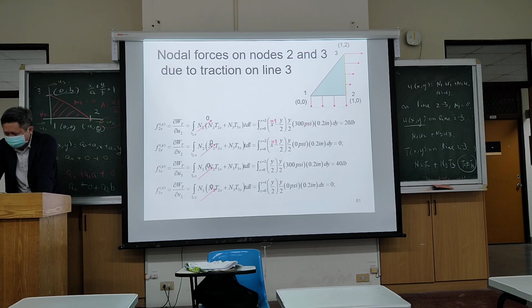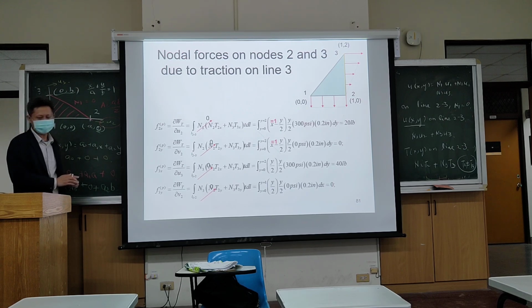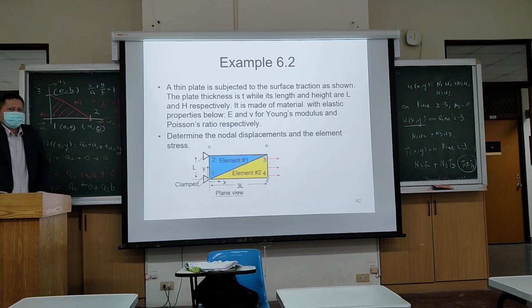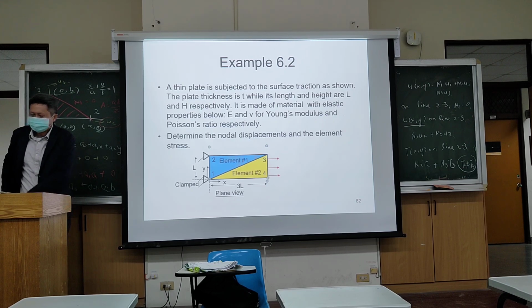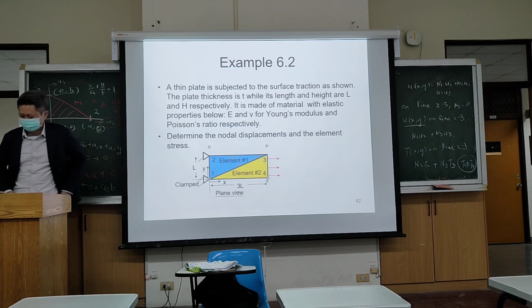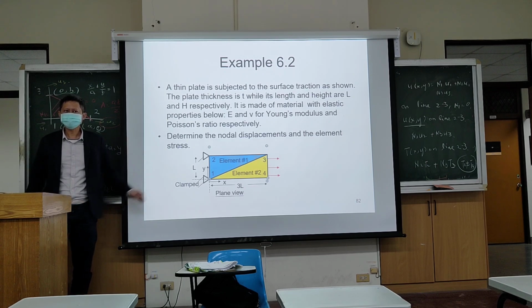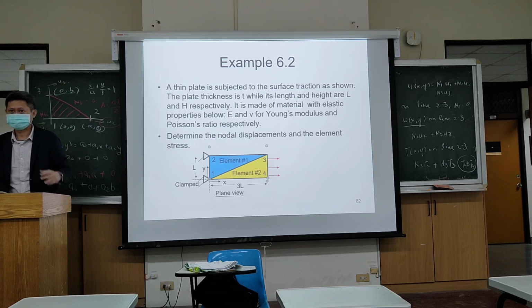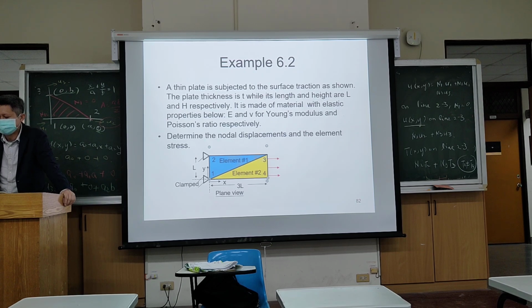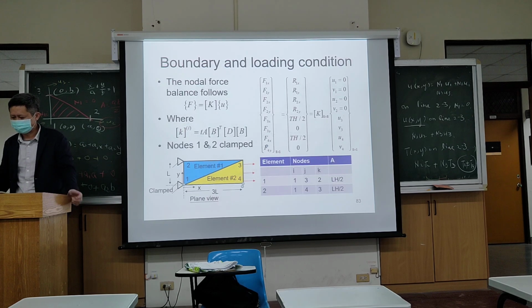And finally, yeah. So after this, we come to the last example. Yeah, this is an example to validate your finite element method. Okay? So remember, finite elements are just approximation. You have to check it against an analytical formula. If now we have a rod being rectangular, and we have a plate being rectangular, it is subjected to uniform forces. How much is your extension? Okay, you should have an analytical formula. So let's see what will turn out.